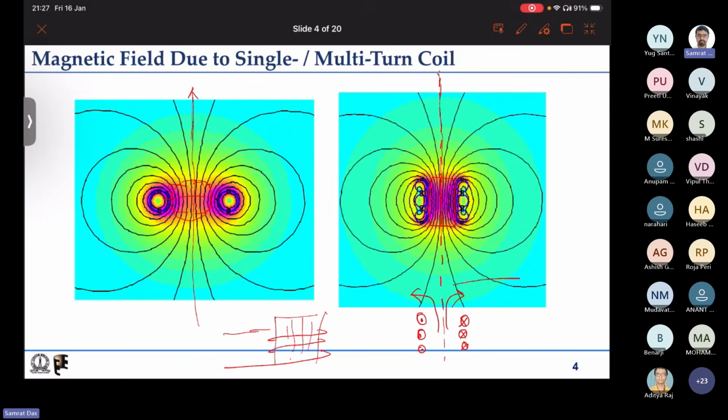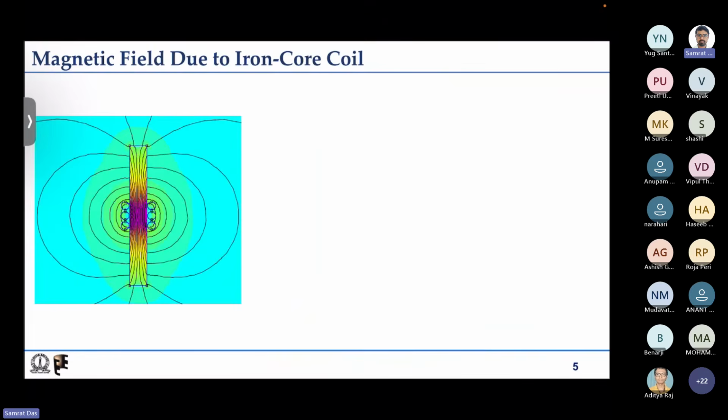So you understand the axis of the magnetic field, and based on the polarities of the currents, it will be upward or downward. If it is dot conductors on the left side and cross conductors on the right side, then with the right hand rule you can see that your thumb points upward, so the magnetic field axis is actually upward. I think this is understood.